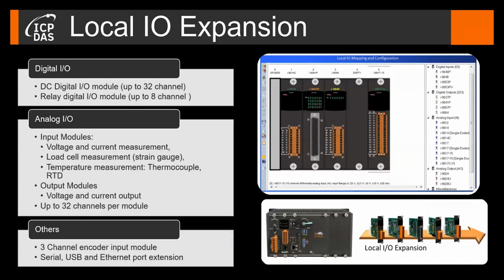As I already mentioned before, our programmable automation controllers are all equipped with expansion slots to expand the local IOs. ICP-DAS offers a large portfolio of IO plugin modules. The Win-GRAF Workbench provides tools for configuring the local IO plugin modules, which is needed, for example, to set the engineering units for analog modules.